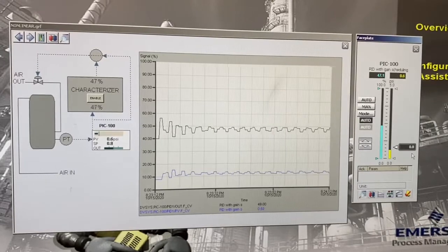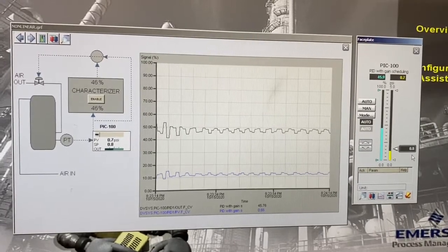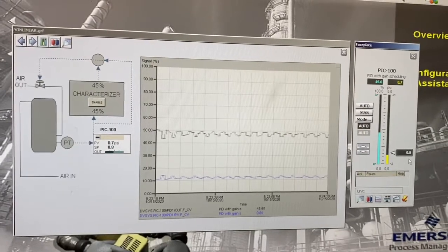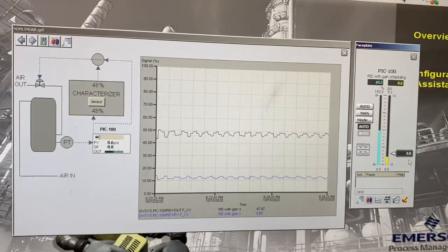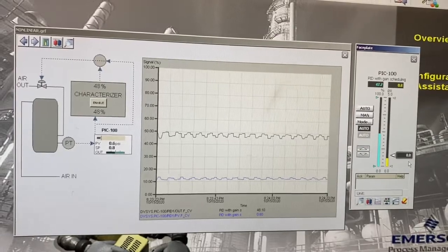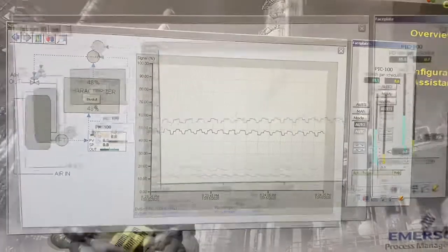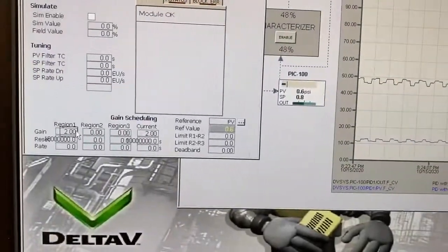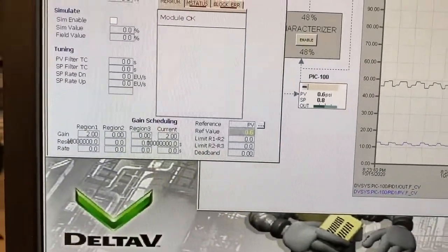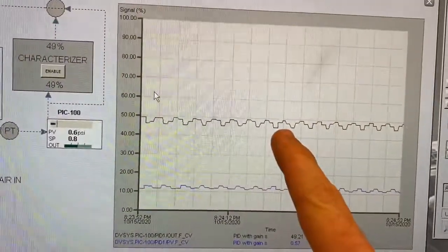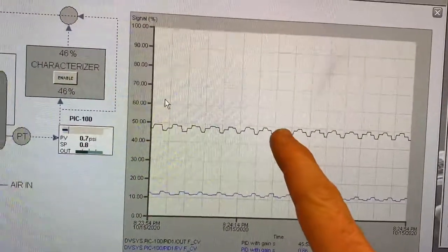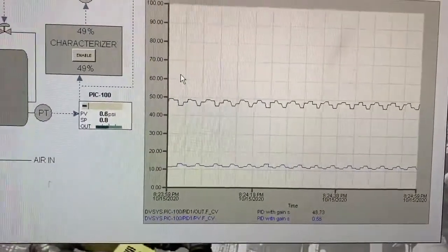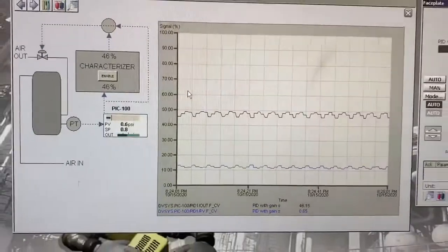So now I'm going to apply the Ziegler-Nichols closed loop tune calculations and enter them into the controller. I'm not going to give those to you because that's something that you're going to have to do for this lab. But I'm going to enter them and we're going to see what happens. Before that, we should probably discuss, we used a proportional gain of 2 here. And it looks like our period of oscillation, peak to peak, is pretty close to one full division here, which is 4 seconds. So we'll use 4 seconds as our period of oscillation.